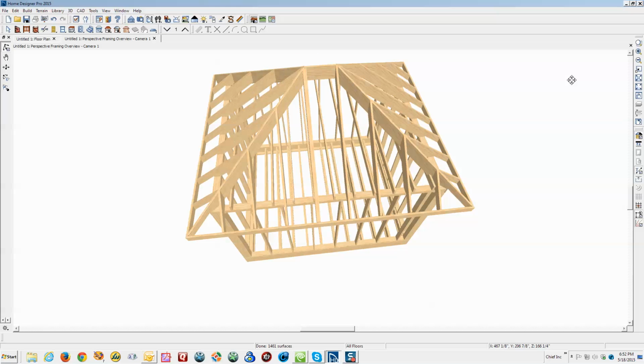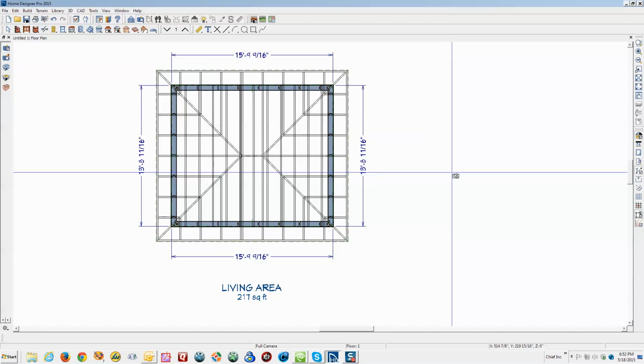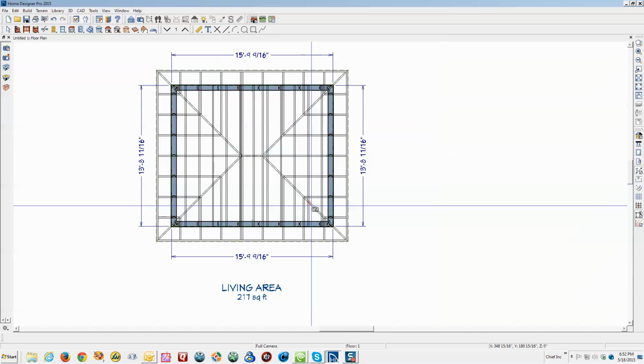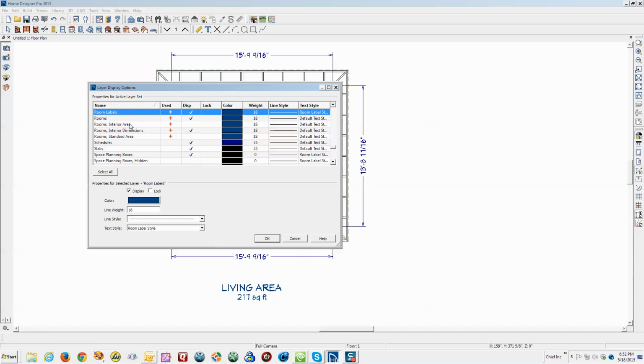When you're doing a framing plan, I never use 3D like this. I mean, I think I have a couple of times. I had worked with an engineer that liked 3D details, and so I worked those out. But normally you're doing stuff in 2D. The first thing is I'm going to turn off all these layers of framing that I'm not particularly working on right now.